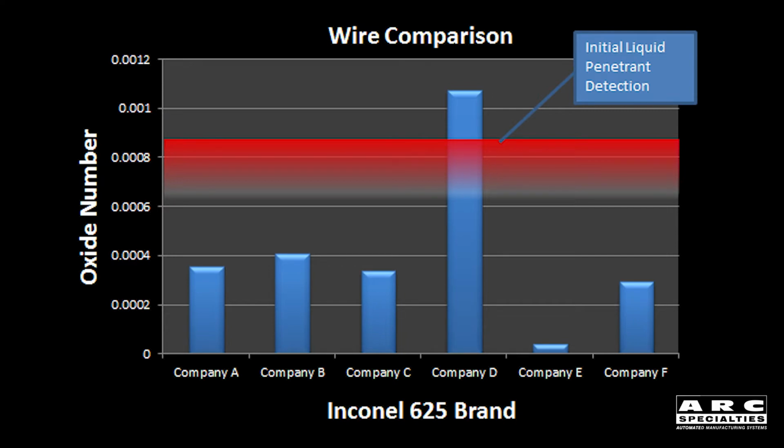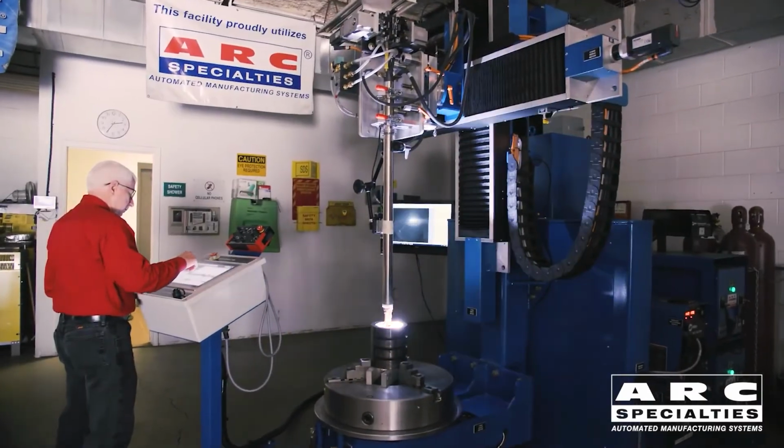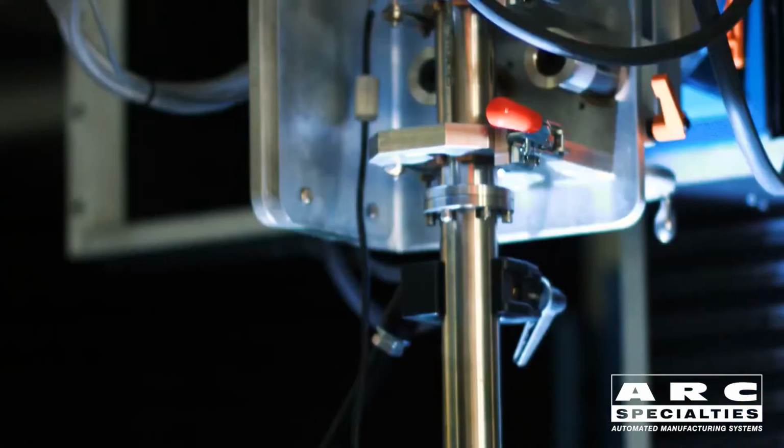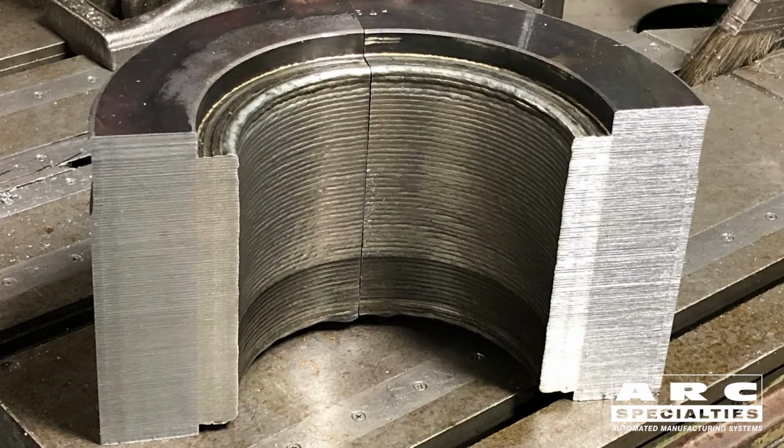My opinion was reinforced this week when Dave Hebel went into our laboratory to produce a weld procedure qualification test. In this case, he wanted to do 3/4 inch thick welds because we're qualifying the weld material as a strength weld rather than simply an overlay. Every 2 layers, Dave had to mechanically remove the oxides from each pass. On the last 2/3 of the final pass, he ran out of wire.